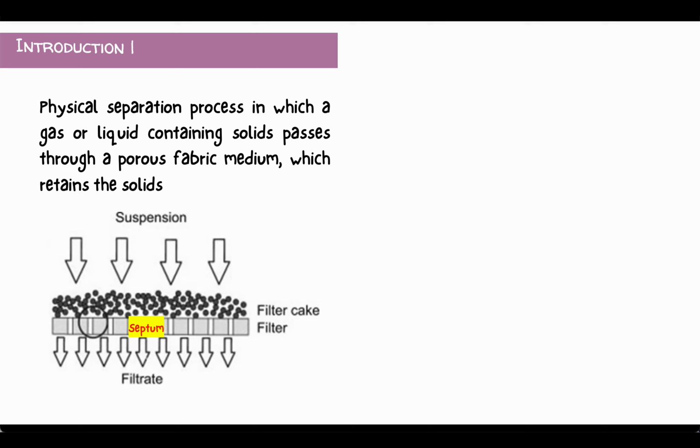The particles are deposited either at the outer surface of the filter medium and or within its depth. The permeation of the fluid phase through the filter medium is connected to a pressure gradient. The liquid more or less thoroughly separated from the solids is called the filtrate, effluent, permeate, or in the case of water treatment, clean water.